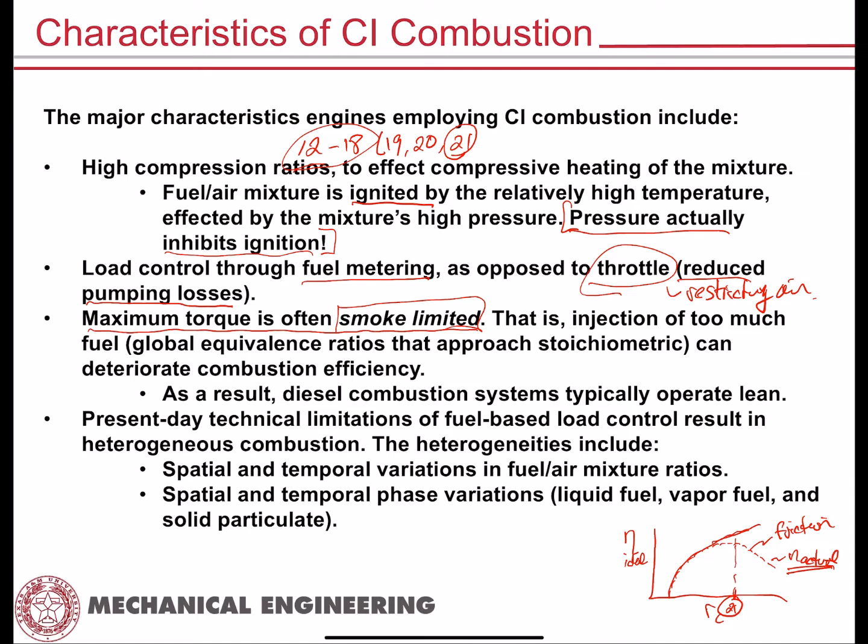That could be other liquid hydrocarbons. It could be gaseous hydrocarbons that can bond to the surface of the soot particle. It could be non-carbonaceous, non-organic substances like any sulfates that might be in the mixture as a result of there being sulfur in the fuel. All kinds of stuff, right? You take all of that, you put it together, and you have what is called particulate matter, okay?